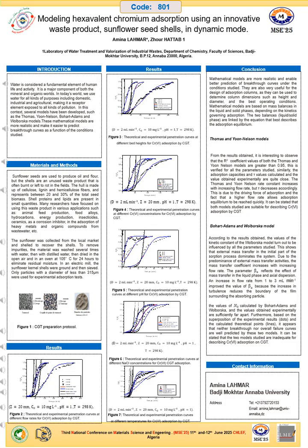Bohart-Adams and Wolborska model. According to the results obtained, the values of the kinetic constant of the Wolborska model turn out to be influenced by all the parameters studied. This shows that external mass transfer in the initial part of the sorption process dominates the system. Due to the predominance of external mass transfer activities, the mass transfer coefficient increases with increasing flow rate.